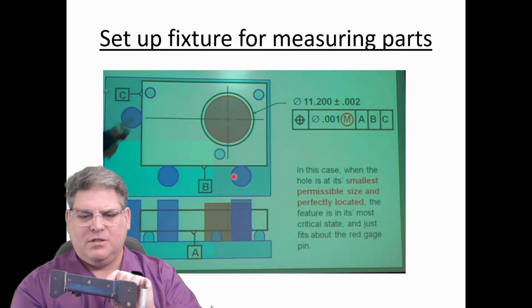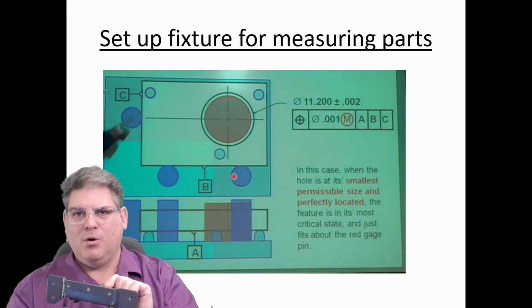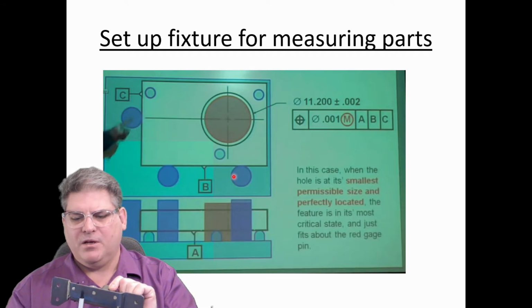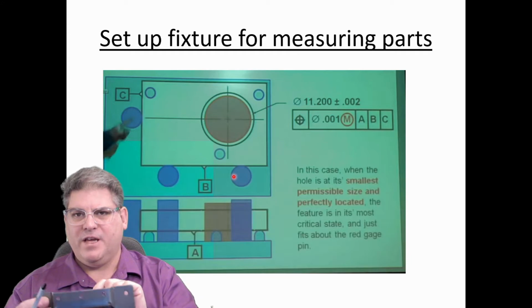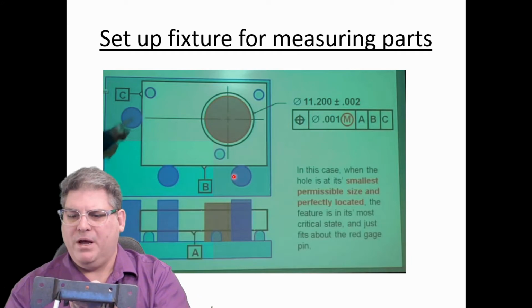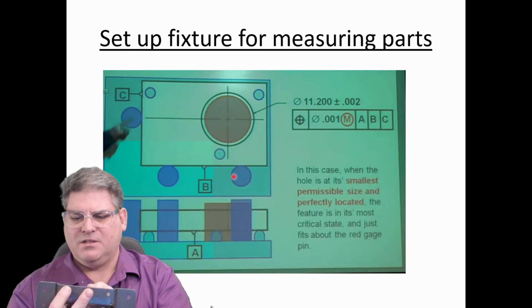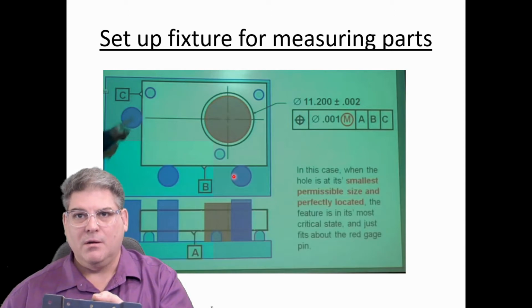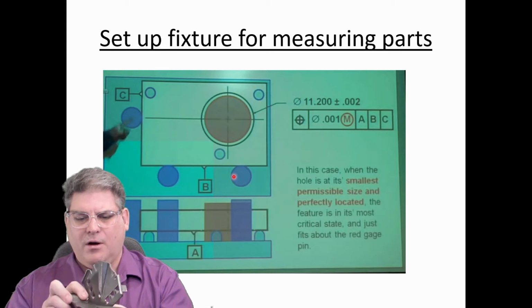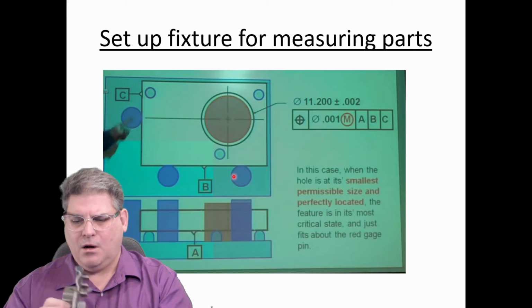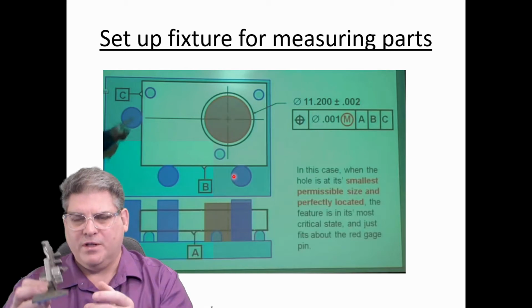Okay, so if this was some rough or bowed surface, we don't really care because we're locating it. And in this case, we would want to pick those mounting points as our controls because that's where it's going to be held on our lawnmower in this case.